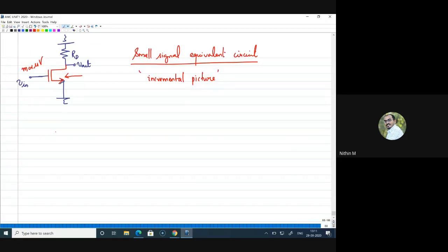Okay, let me just explain this. If you are providing a DC VGS, there will be a DC current for sure. Now, on that DC VGS, I am giving a small vgs. That is now my V in. That means I will actually get a current ID. This is the picture you should have in your mind. Now I am replacing MOSFET. Since MOSFET is given in red color, I will draw the incremental picture or the equivalent circuit of MOSFET first.